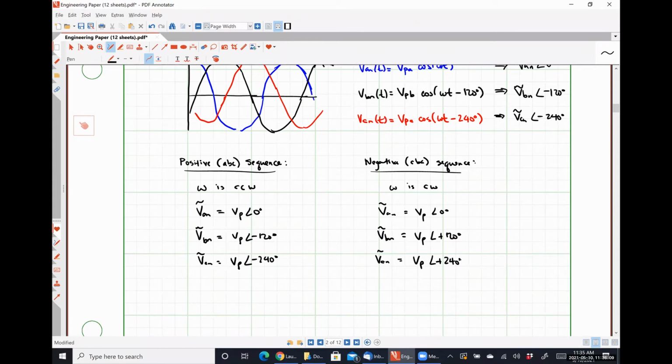If you go to the door, if you go that way, and then take a left down that hallway before the exit door, there is a rack that has 3 electric machine rotors on it, so that you can go look at them if you ever particularly felt like it. But it's just a long shaft with electromagnetic coils on it. That's all it is. We don't actually use a permanent magnet in 3-phase machines because it would be too expensive. We use electromagnets to do it, but it's all the same.